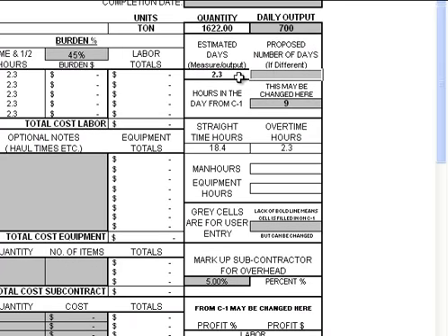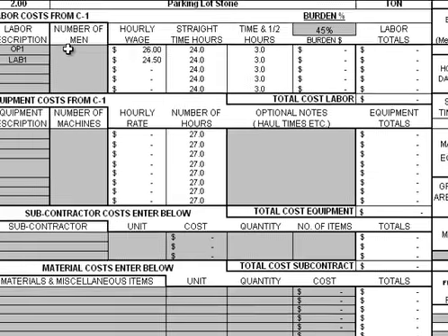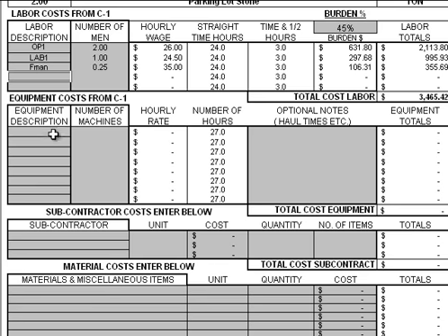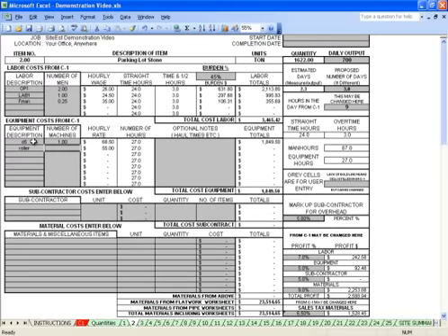Well, with traffic and all, maybe I'd better allow for 3 full days. And I'm going to have 2 operators and a laborer on this particular project. The foreman is going to be there 25% of the time. Now I'm going to put a D5 on this, 1 machine. I'm going to put a roller on it, 1 machine.